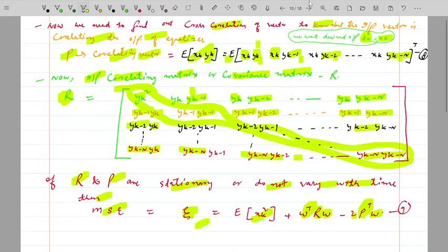So this is the training part of this equalizer. If we minimize this MSE equation, equation 9, in terms of the weight vector W of k, then it becomes possible to adaptively tune the equalizer to provide a flat spectral response, or minimal intersymbol interference in the received signal.